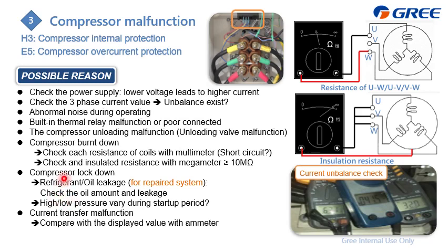And if it is locked down, you can also check it at the startup period, which is to check the high and low pressure. If it changes a lot, that means it is not locked down. If it is almost no change, that is locked down.